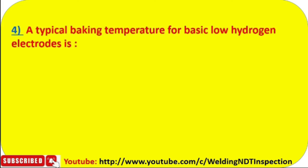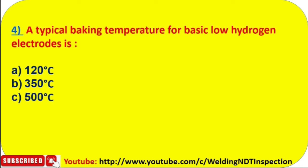Question number 4. A typical baking temperature for a basic low hydrogen electrode is: what is the typical temperature for baking a basic low hydrogen electrode? A is 120 degree centigrade, B is 350 degree centigrade, C is 500 degree centigrade, D is 200 degree centigrade. I think you should know.